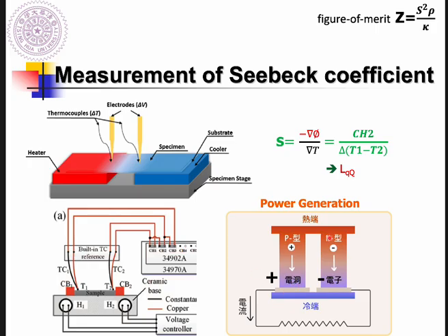And on the other side we use N-type materials. The same idea. We do have a hotter side, which means that the major carrier electrons have higher energy. They tend to go to somewhere with low energy. So the electrons tend to go downward, right? So that will lead the potential at this side to be lower.